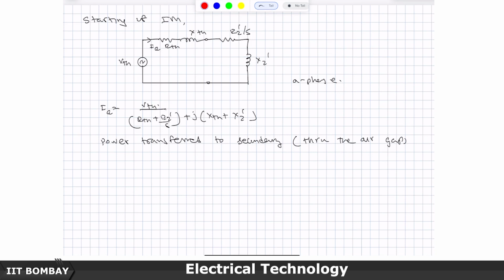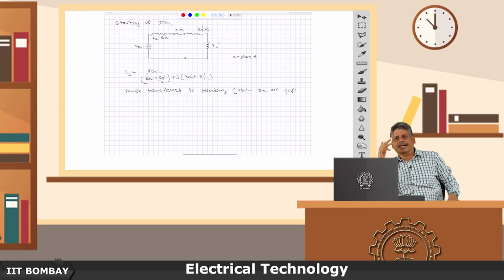So, that is why, if you recall, I had explained to you that induction machine is called a generalized transformer. The secondary winding here has a freedom to rotate. In a normal transformer, the secondary winding does not have a freedom to rotate. Because it has the freedom to rotate, the frequency of the rotor currents is different from the frequency of the stator currents, which are of course tied to the frequency of the supply.